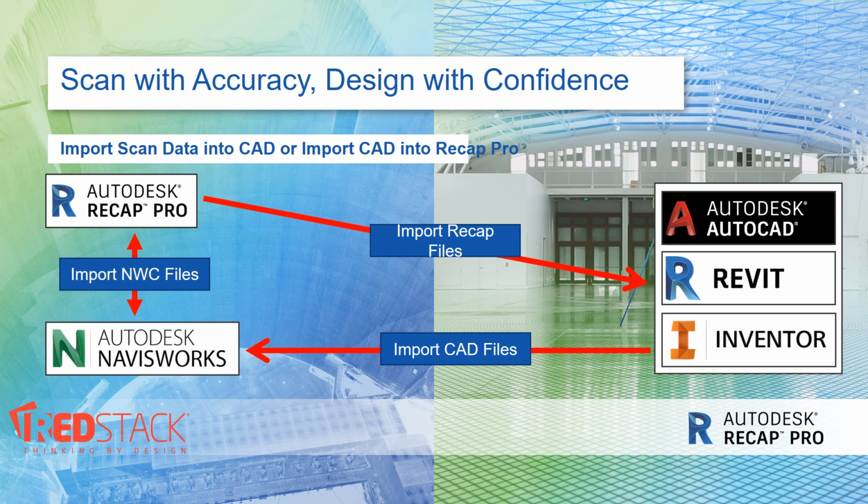So you import the scanned data into ReCap Pro and create ReCap Pro projects. On the right here, we've got popular Autodesk CAD applications, and at the bottom there, we've got Autodesk Navisworks, which is a data aggregation tool amongst other things. So you import your CAD files into Navisworks, and you can then attach Navisworks NWD, actually not NWC, NWD files into ReCap Pro, or you can attach ReCap projects into Navisworks.